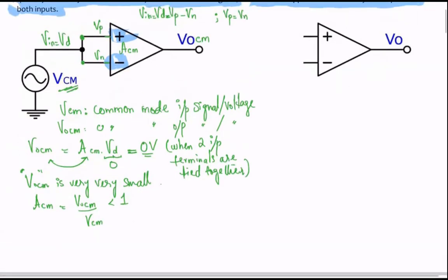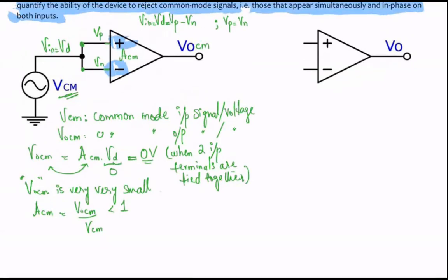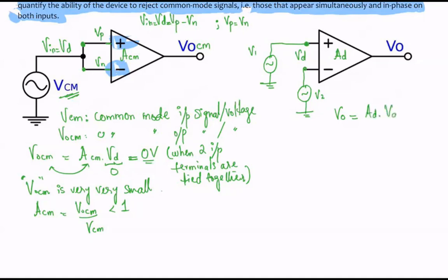Now also, let's come to the graphic on the right hand side. Say I have positive terminal which is connected to some input signal, and then also I have another input signal here. And I say this is V2, this is V1. The potential difference between these two signals, say VD. This amplifier has some gain, differential gain A. So what is the output equation here? Can anybody tell me what is going to be the output voltage equation? Yes, folks. A times VD. Okay, AD times VD, that is correct.